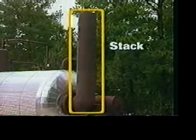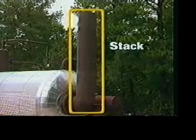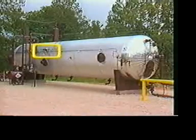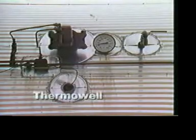The firebox contains a gas burner which provides the heat source for the treater. The stack is a metal cylinder where exhaust gases are vented after flowing through the fire tube. The thermometer shows a pumper the temperature at which the emulsion is being treated. The thermowell provides a location for the thermostat temperature probe, which helps maintain the desired treating temperature.